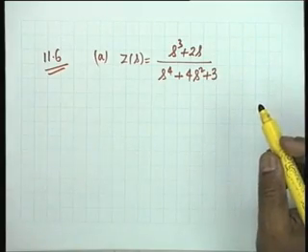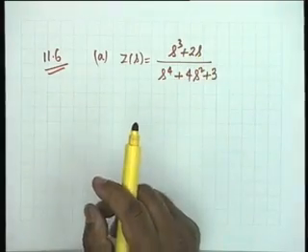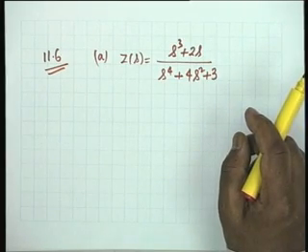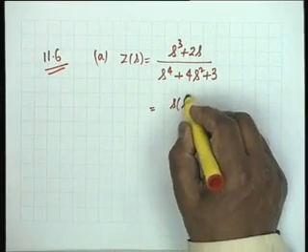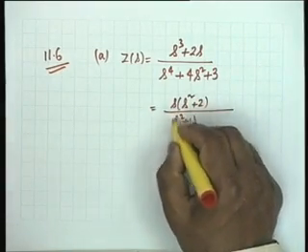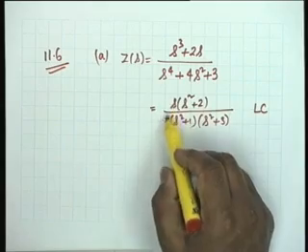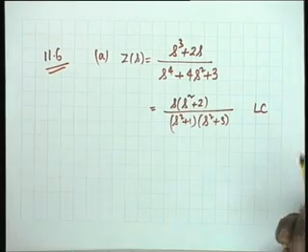Now, you have to decide whether it is RC, LC or RL. If it is RL, we do not know yet, but let us look at it. Now, obviously you see it is an odd rational function, is that not right? It is odd, therefore, it cannot be RC or RL. If it is at all realizable, it has to be LC. Let us look at that. S times S square plus 2, if you can factorize, do that. S square plus 1, S square plus 3. So, it can be realized as an LC, because the poles and zeros alternate: 0, 1, 2, 3. Okay. Part B.